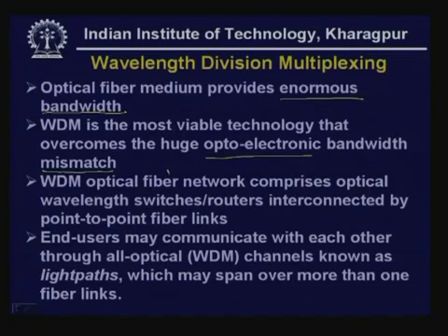On the other hand, individual users who are sending either audio or video, their bandwidth requirement is smaller, and only by using wavelength division multiplexing we can share an optical fiber, and we can make use of the enormous bandwidth, and it also overcomes the huge optoelectronic bandwidth mismatch.